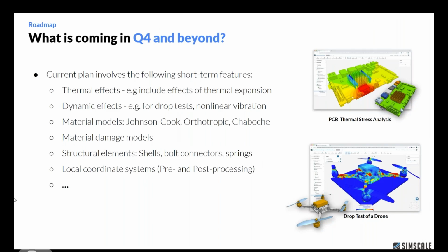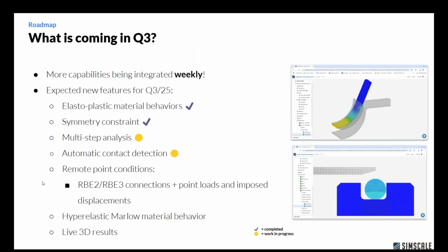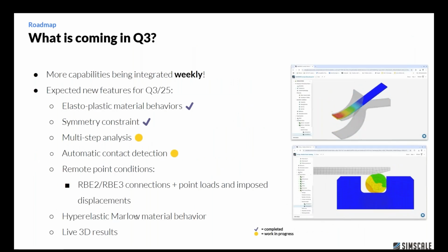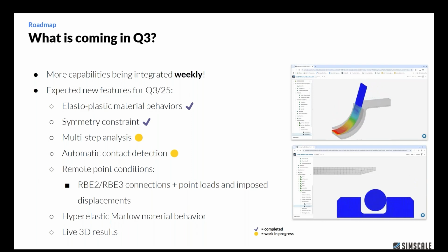So currently we have linear elastic, obviously, and hyper-elastic models of 2 types: Mooney-Rivlin type and Ogden material. And we will add more. In this quarter, on the Q3 slide, we'll add Marlow material. That's very convenient to add hyper-elastic materials from a pure test data set.